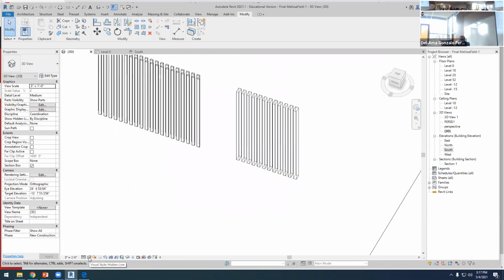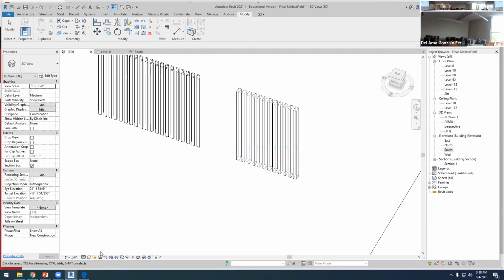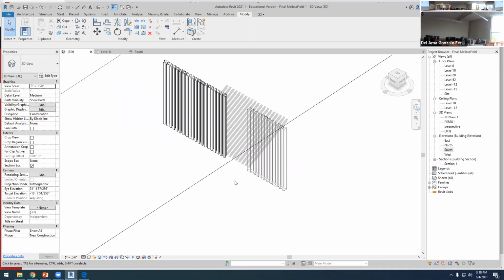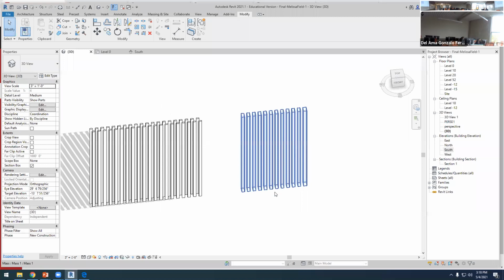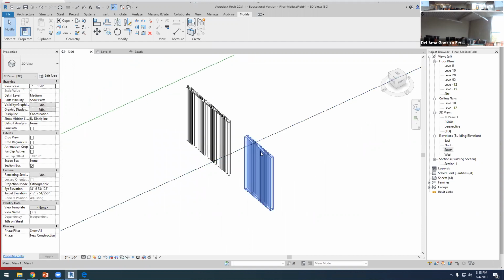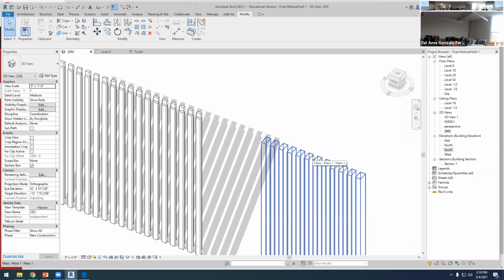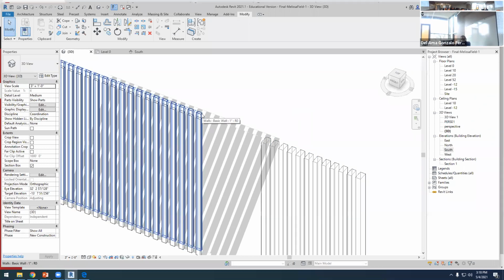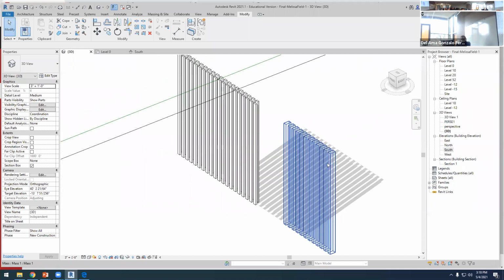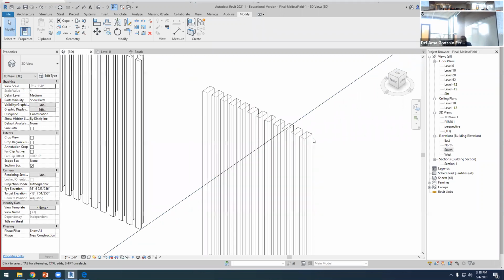If we cast shadows, see. Well, that's interesting. This one doesn't cast shadow. It's not because it's on fire or something like that. It's because it's still a mass. Okay, so I have assigned a material to this one, but this is still a mass. And when we have masses, it doesn't cast shadows. How can we define a mass here?